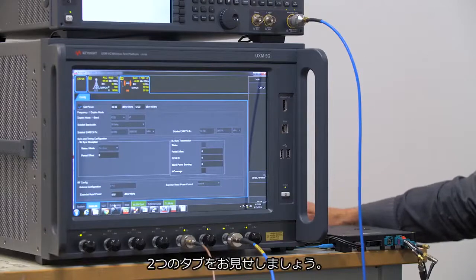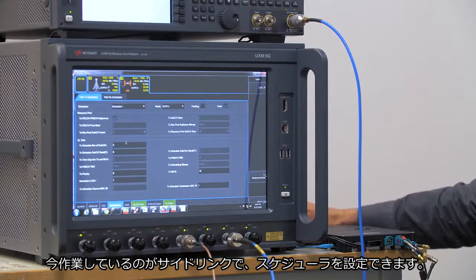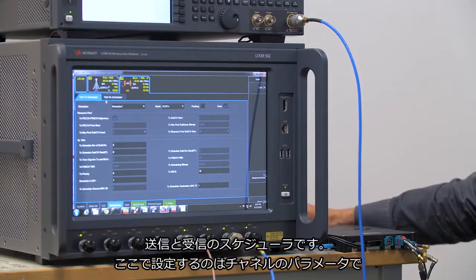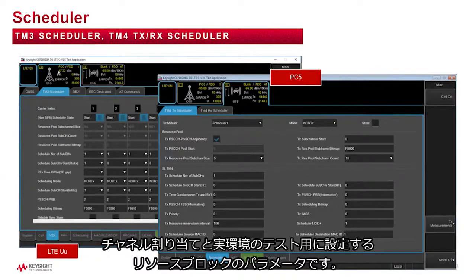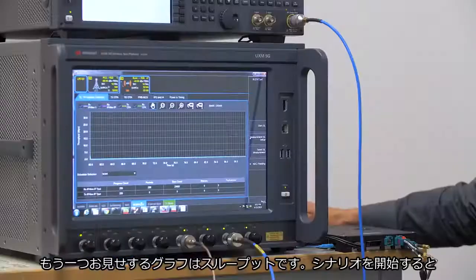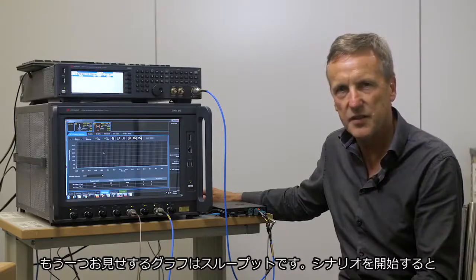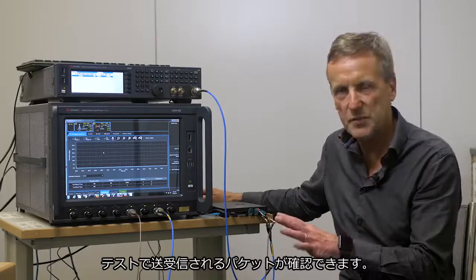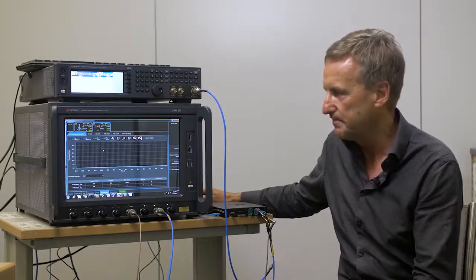A couple of tabs I'd like to show you. Here we're working on the side link, and we can set up what we call our schedulers, both transmission and receive scheduler. These set up the channel parameters for allowing the channel allocations, the resource blocks, to be set for testing in a real-world environment. The other graph I'm going to show is our throughput, and when I start the scenario, we will see the transmission, the packets being transmitted and received as part of the test.